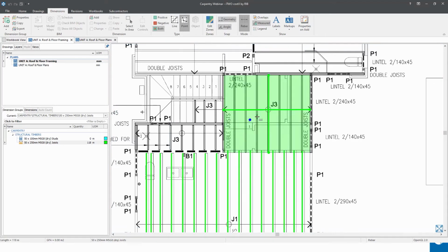Just update. And if I hover back over this quantity, it's telling me 9 joists. Yes, we saw it calculate that. The total length of those, the installed or cut length on site, will be 27.79 meters. But to achieve that, I need to go out and buy 9 3.3 meter lengths. The length was 3.1. The nearest increment of 300 above that would be 3.3. And there's the spacing at 450 centers.